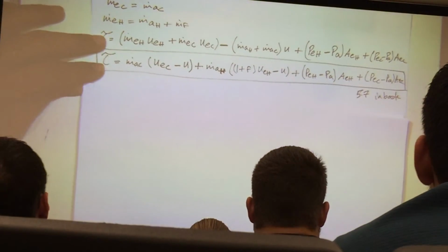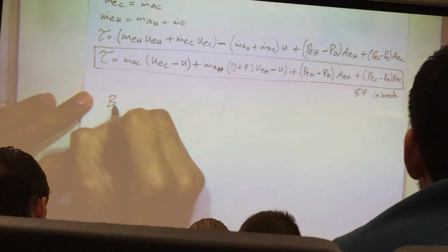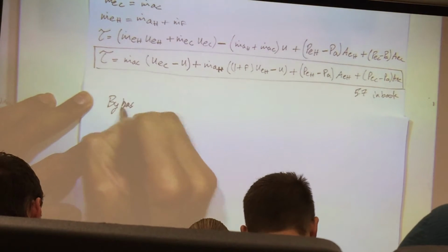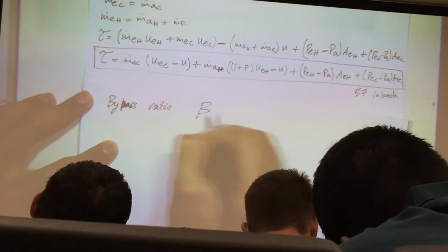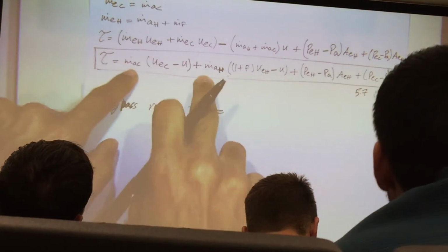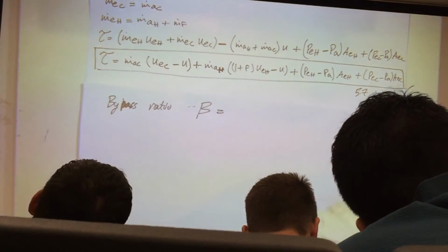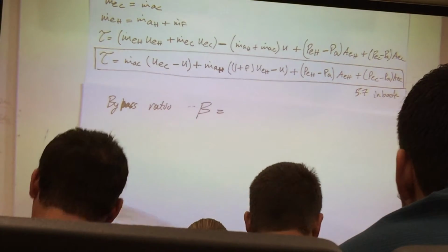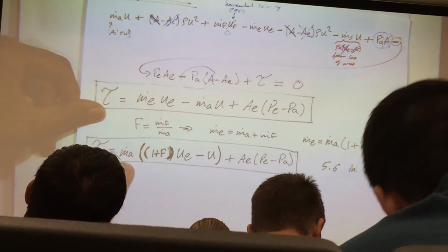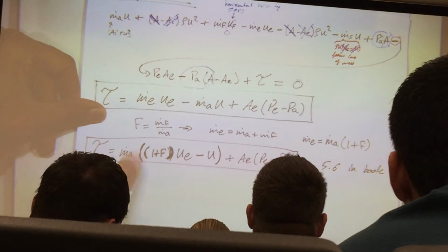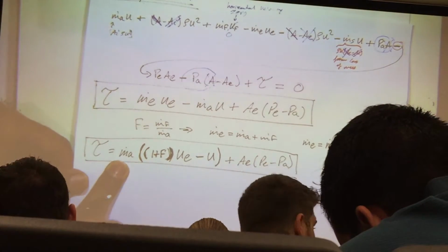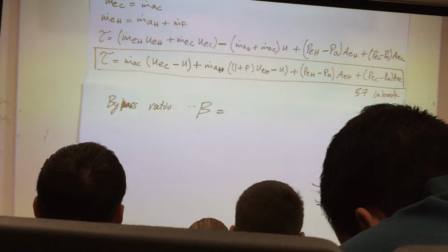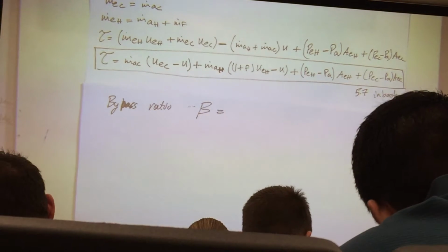Now, we're going to tailor this a little bit more later on when we actually go over turbofans by the bypass ratio, which is beta. And the bypass ratio says, well, I have two masses here. If I compare my equation that I had before for turbojets, we only have the inlet mass that's going through my engine, the air that I'm slugging through the engine specifically. This is primarily okay for military engines, but for commercial engines, we're after higher efficiency. So to do this, we have to rely on a bypass ratio.